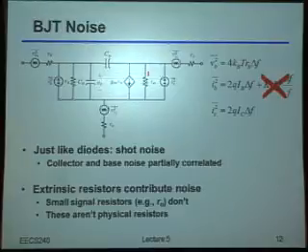Output conductance is really just your way of modeling what happens locally if you change some voltage in that device. But these small signal elements don't really generate noise because they're not actual physical resistors. They're just your model for a whole pile of other stuff that could be happening under the hood. So whenever you're talking about noise, you always have to model the noise sources due to the real fundamental physics of the device, and then add them into the small signal model, which could be abstracting a whole bunch of other things underneath it. Does this make sense to everybody?